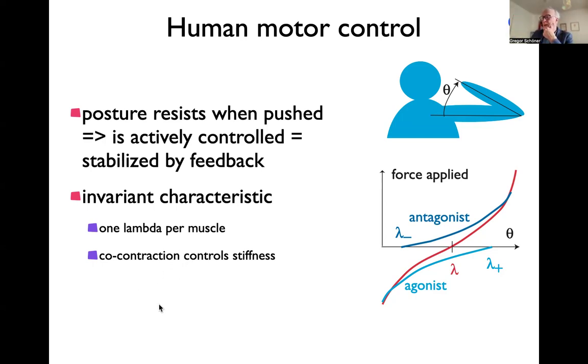This is like having a motor, but also a spring in series, and that gives the joint a little bit of a spring-like property. If the spring is very stiff, it's just used to measure torque, and there are some torque-controlled motors that way. But if the spring is relatively soft, then it emulates human movement, which avoids using this very large amount of force, which is dangerous, can break things.